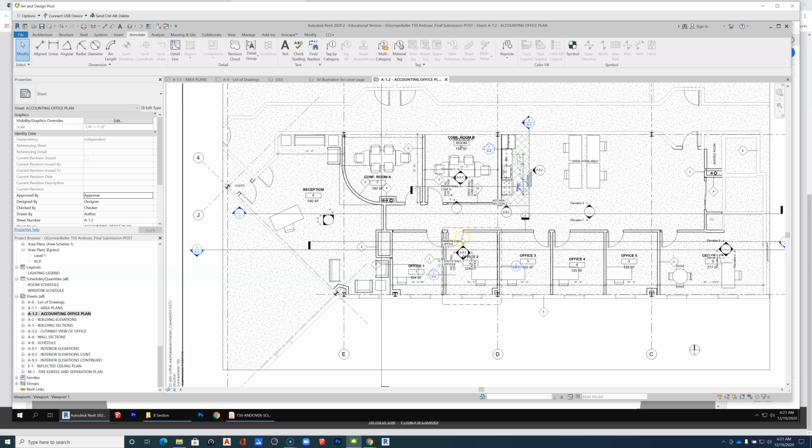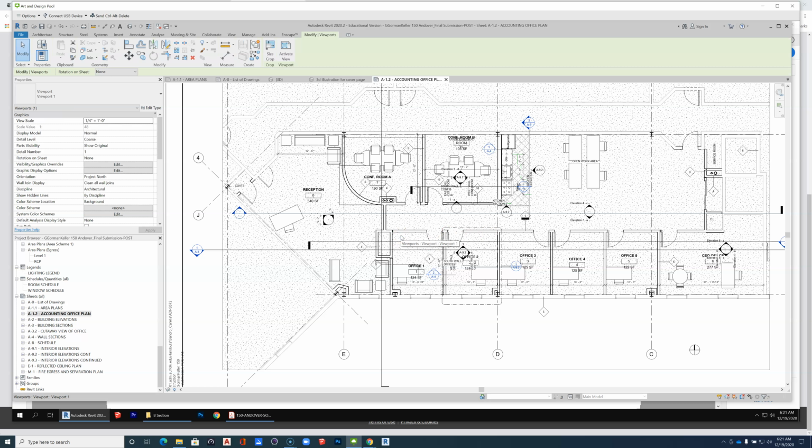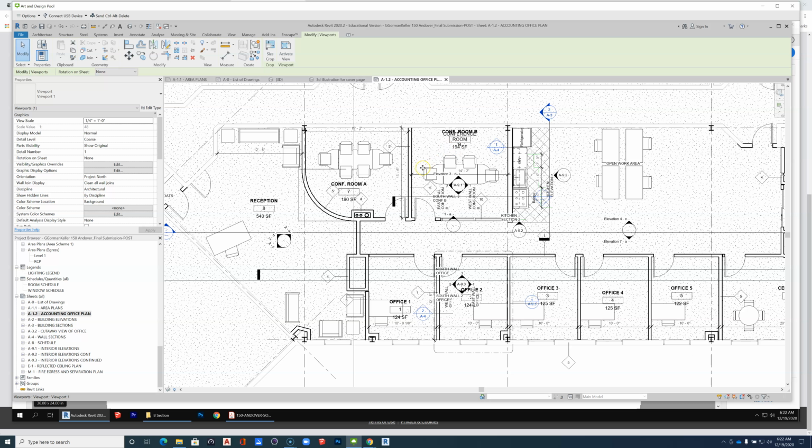Remember, we could improve the legibility of the plan by taking out that hatch surface pattern on the concrete floor. And then we selected parts of the floor, split face areas, and drew different materials into parts of the flooring. For instance, wood flooring in the conference room, tile in the kitchen, etc., etc. So let's have a look at how to improve the visibility settings of this drawing.